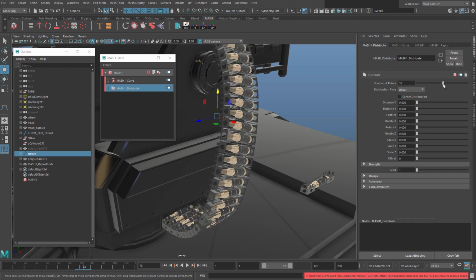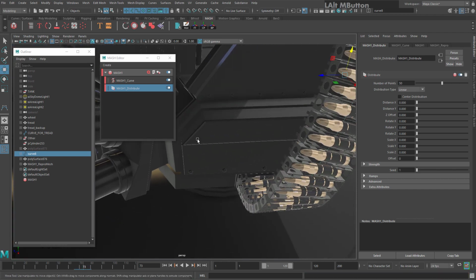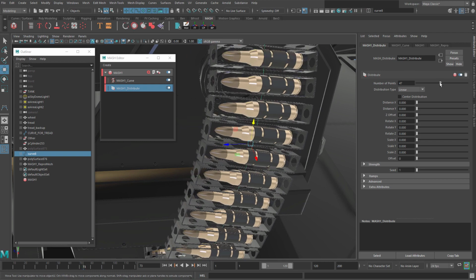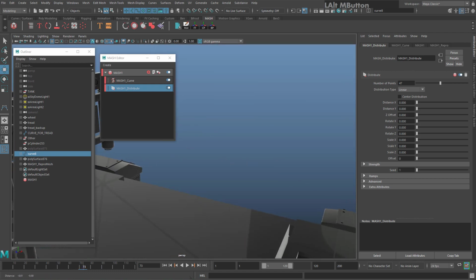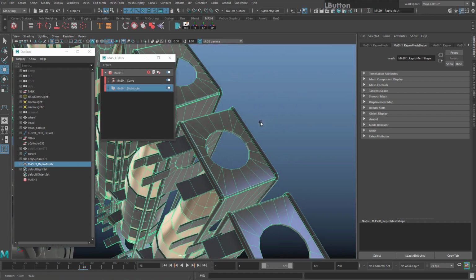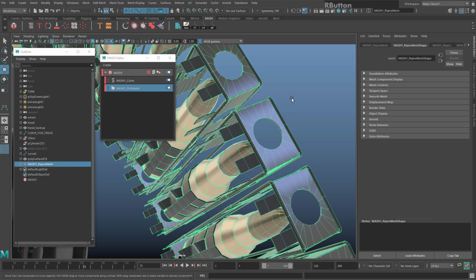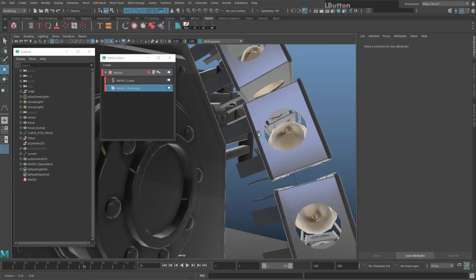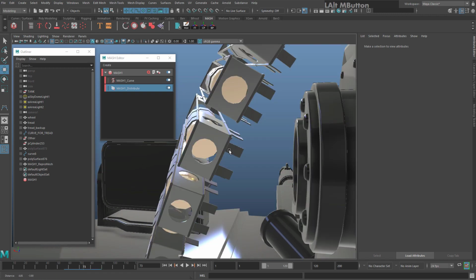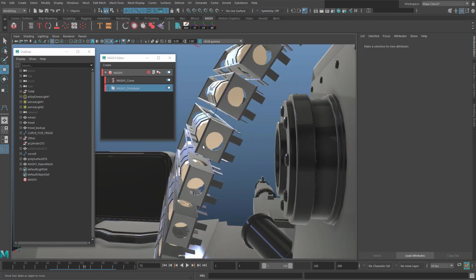And obviously, this is why we had to keep our scene low poly, because it goes absolutely wild with the poly count here. And you can see we've got a bit of a problem, and this will happen to everyone, where the geometry is facing the wrong way like this here. So I did this intentionally because it's going to happen to you. So what you need to do is look at a single one of these and figure out what you would need to do to correct the position.